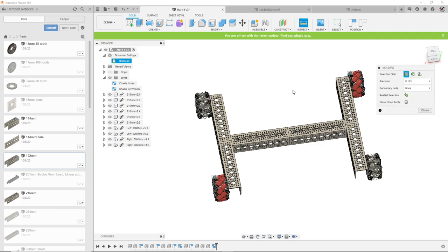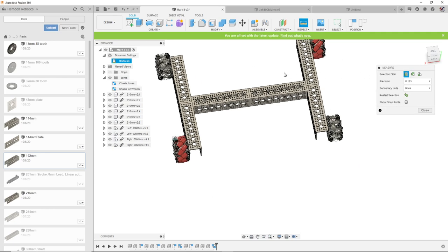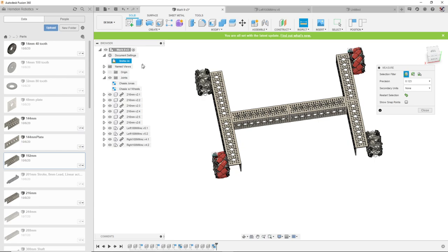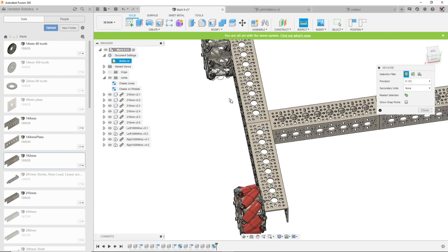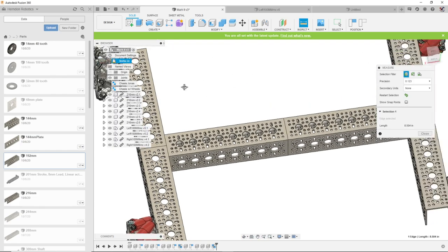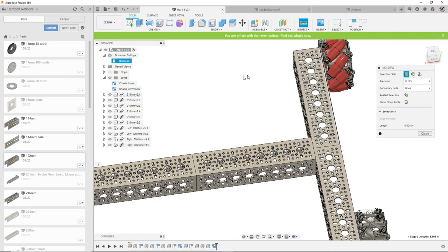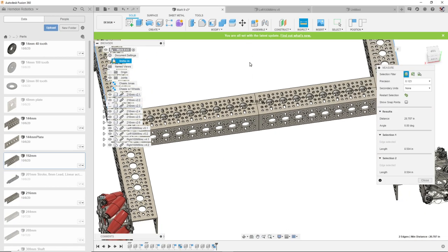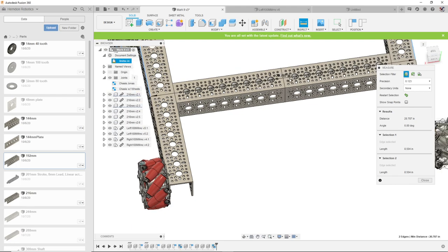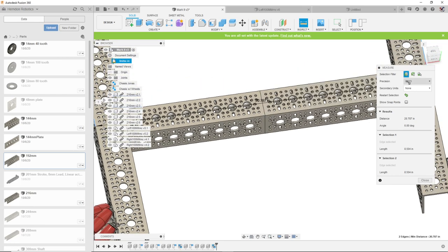And, oh, measurement, forgot to do measurement. Let's say you need to take a measurement of something. It'll go by your default unit, which is that. All you do is, once again, point to plane, etc. If I do point to point, you'll see it says it's 20.78 inches, and that's because it goes to the thousandths place for precision, or 3 sig figs, some chemistry terms in there.